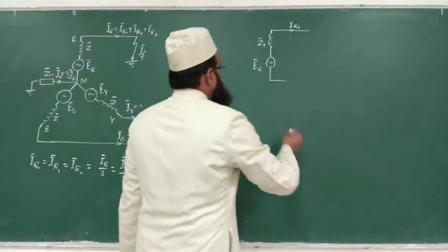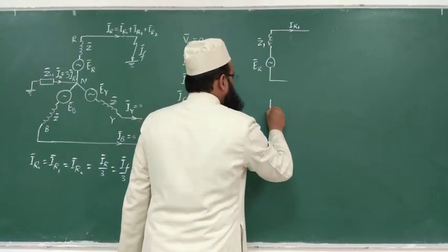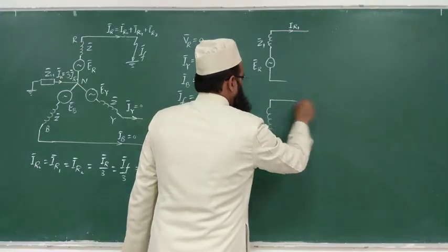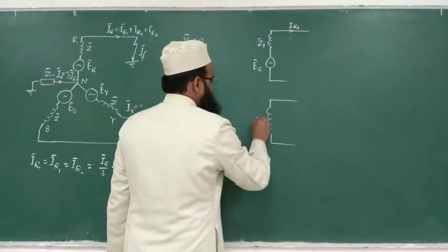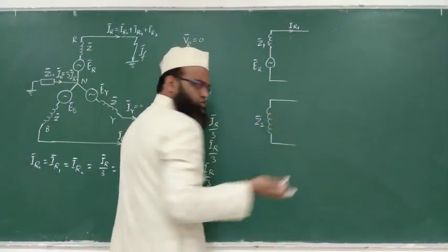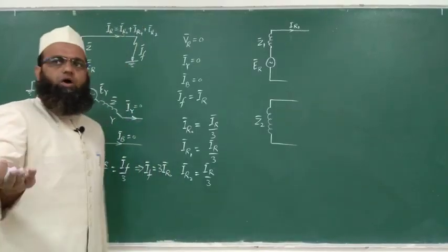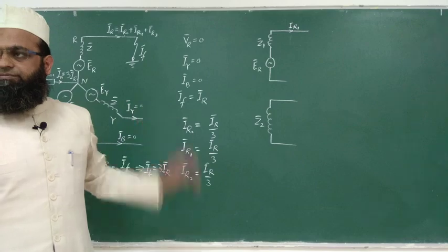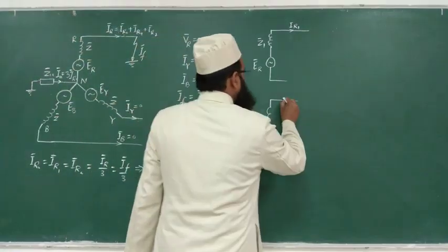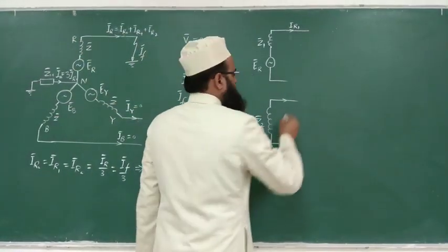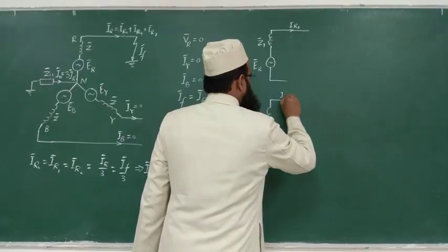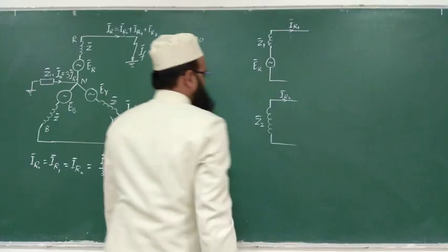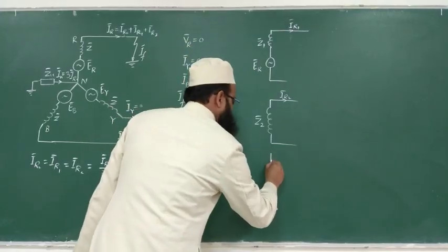Okay. Similarly, draw negative sequence network. So let us represent this as Z2. We know how to find the values of Z1, Z2 knowing the system impedance. And current through this will be IR2, fine, this phasor. And what about zero sequence impedance?